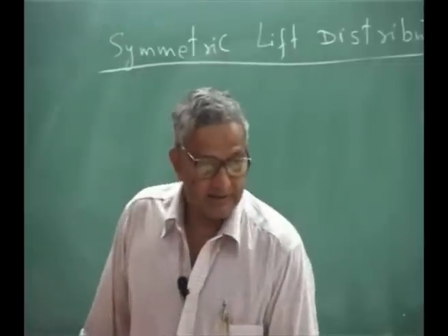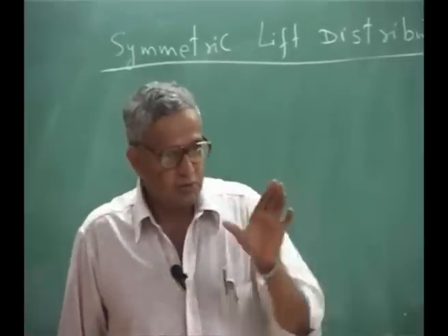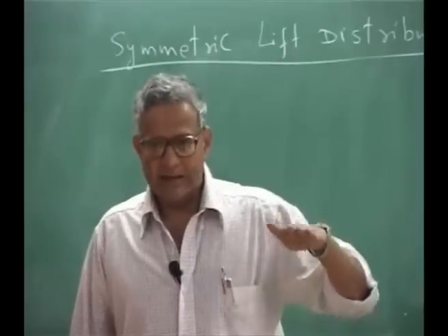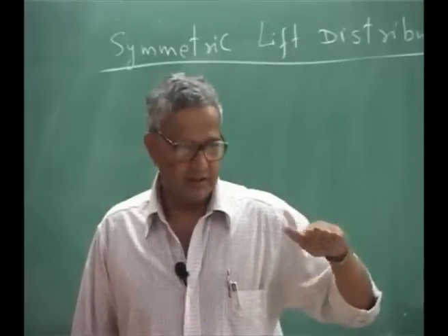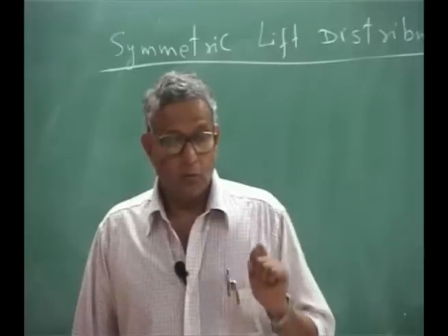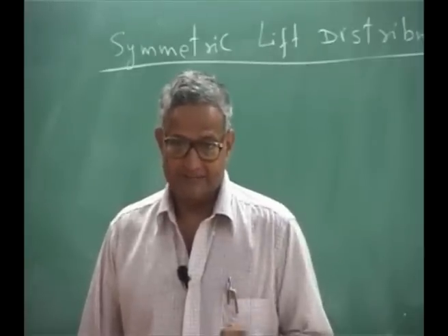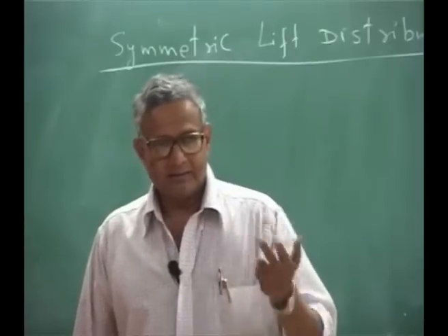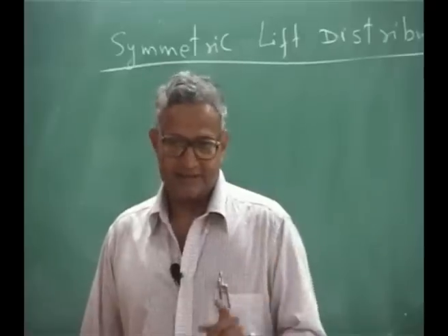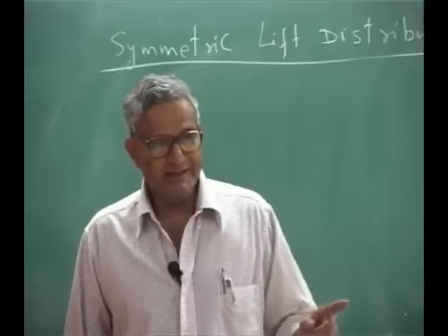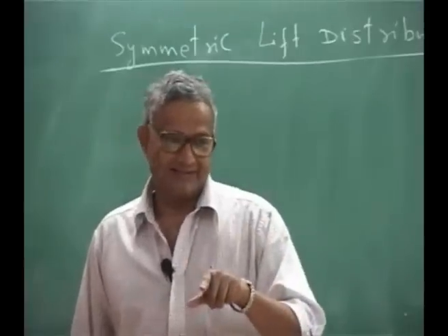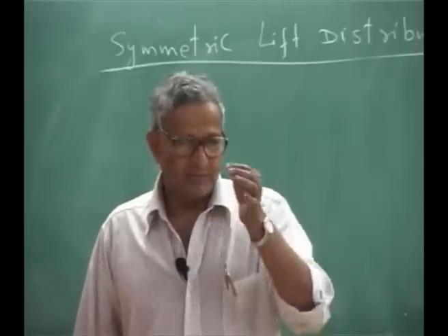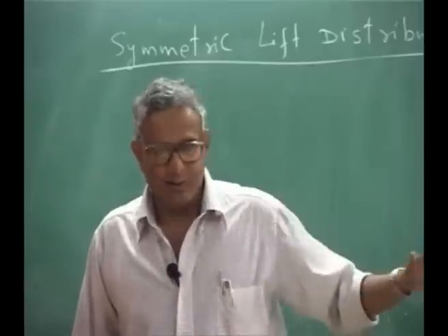Okay. And in this, suppose there are two types of problems one can always look at. Given the initial angle of attack, that we call the rigid angle of attack, what is the load factor I am going to generate? The second problem is, given the load factor, what should be my rigid angle of attack? Because load factor is related to how much it is going to lift. Lift by weight is my load factor.